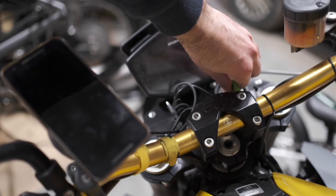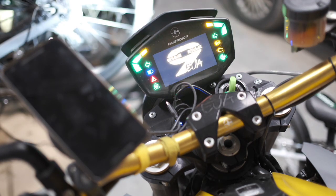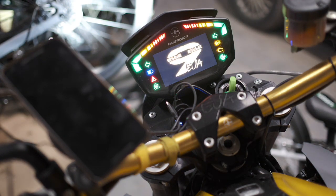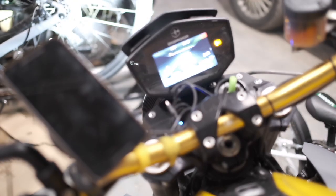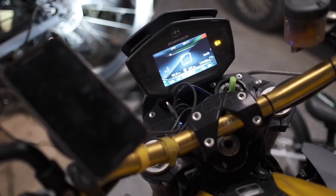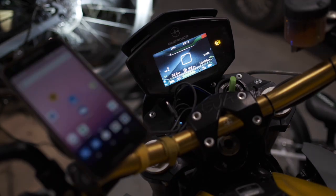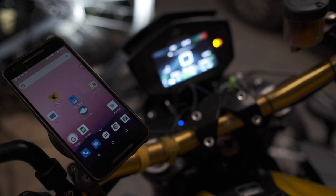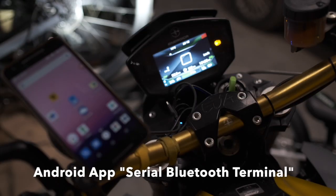Okay, I'll be sharing my phone anyway, and you can either use an OBD2 Bluetooth dongle or a wired connection. The connection itself is underneath the left tank cover, and I can show that if you want as well. The software on a computer I would recommend is SavvyCAN, and for an Android device I use this Bluetooth terminal.